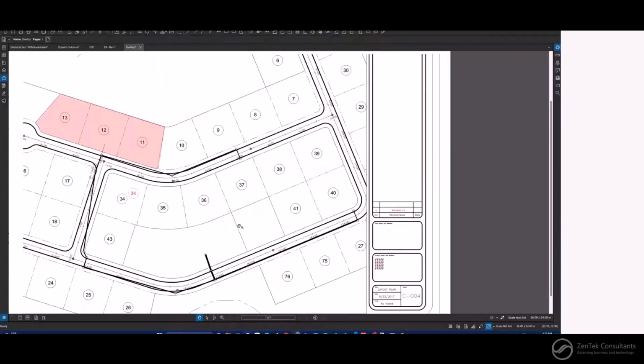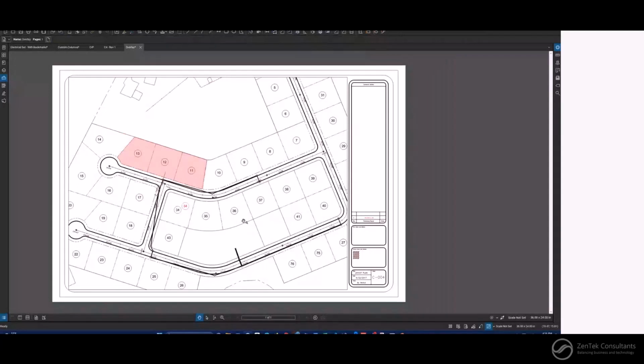So again, some great examples I used in the field. I would always lay down the architectural drawings as my base layer, and I would start putting in other trades that typically do have conflicts with each other. One of the biggest ones was always our millwork and our electrical.